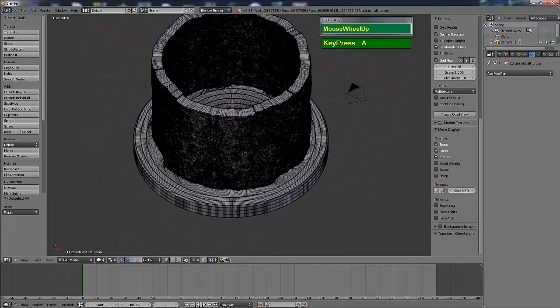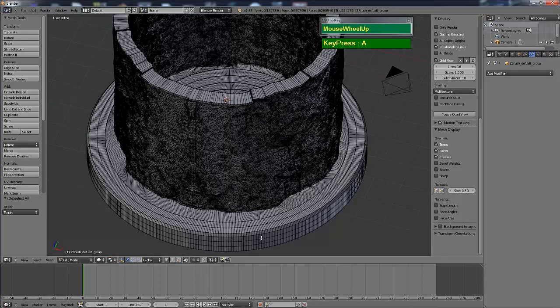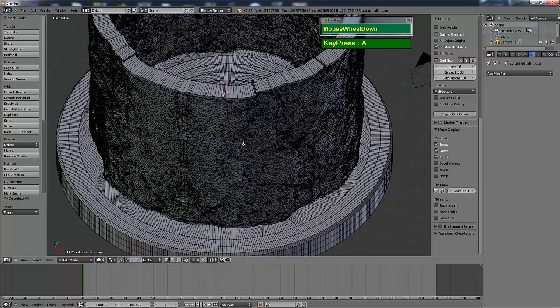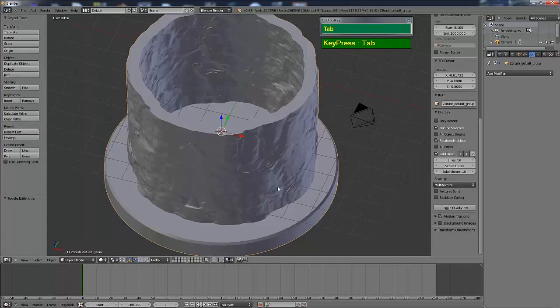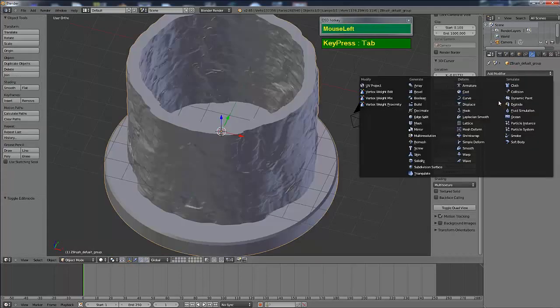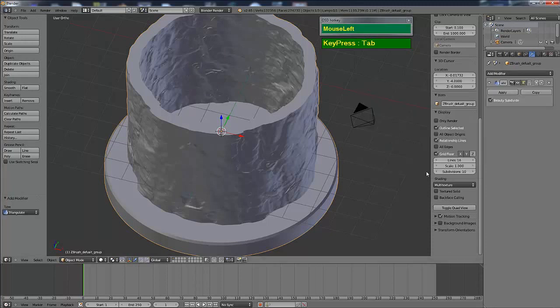But before you can 3D print it, you need to change all these four-sided faces into three-sided faces. So you need to apply a modifier. But before you do that, let me go to object mode first. Then apply modifier and choose Triangulate. Alright, and then hit apply.